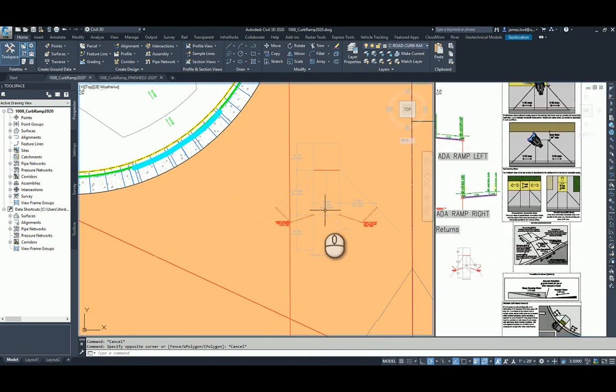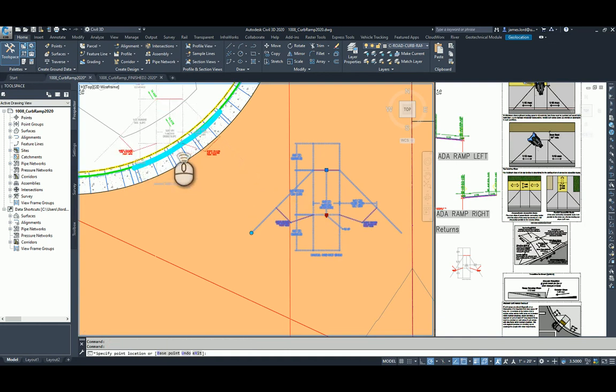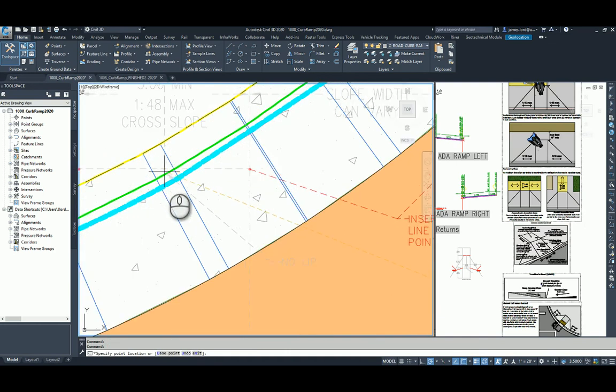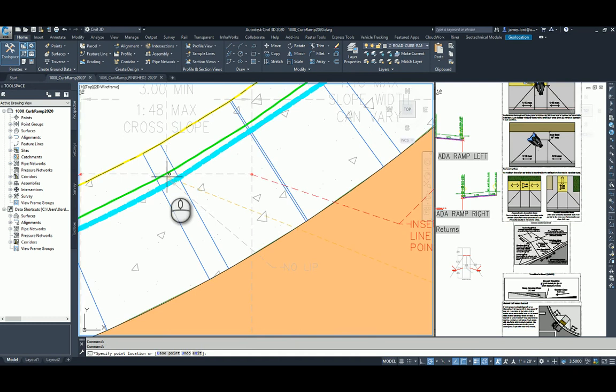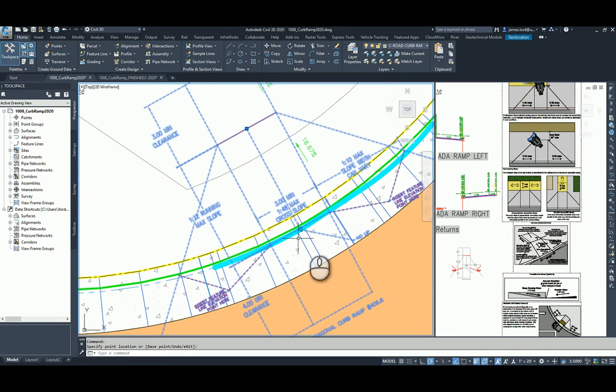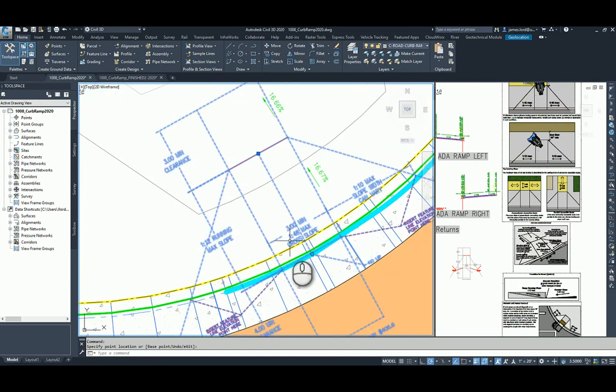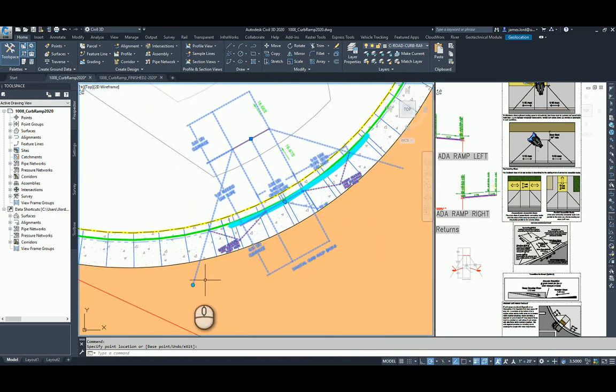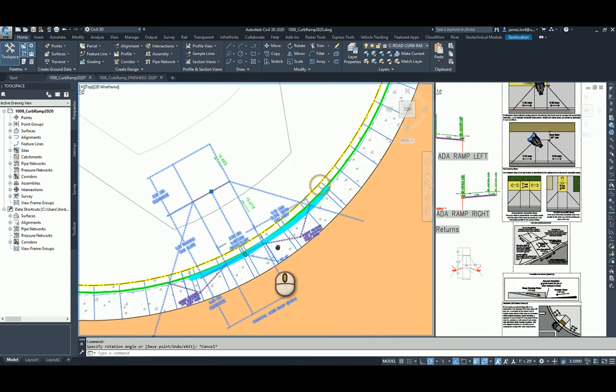Basically, I'm going to take this little curb ramp here, and with this align parameter, I'm going to align it to this little feature that I have right here. That's what the align parameter does, because without using the align command and trying to rotate, it's pretty awesome. All your dynamic blocks should have that on there. Then I'm going to adjust the flares if I need to, depending on where I need them. I would just draw it out to wherever it's going to be.